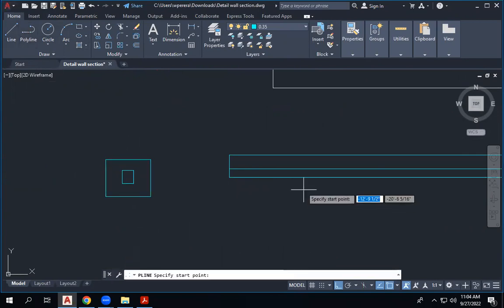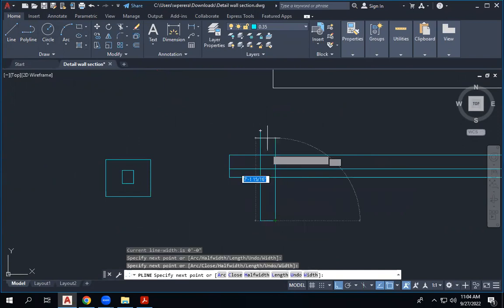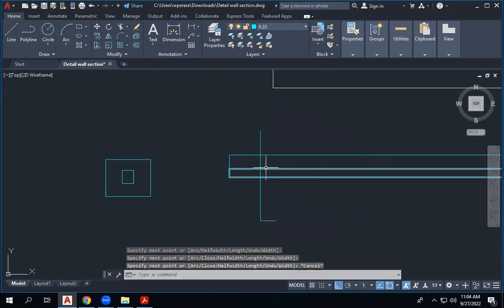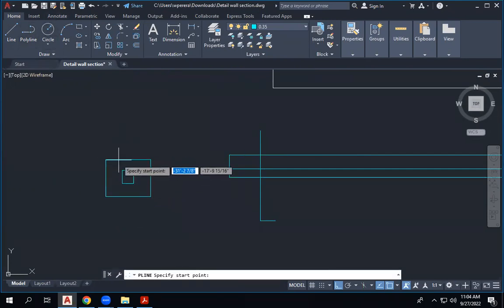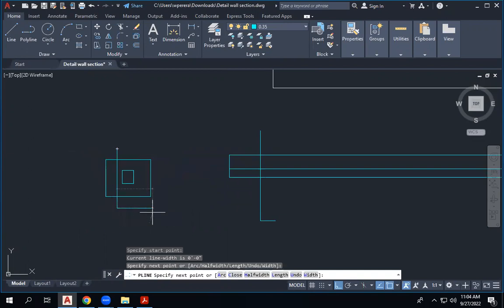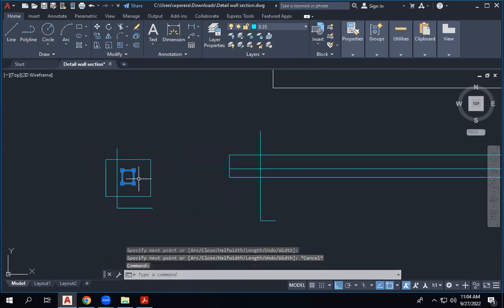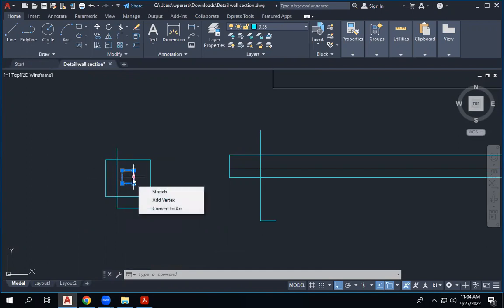So if you cut it here, you see all the way, the wall section and the footing section. But in the wall foundation here, if you cut it here, what you see is the column in elevation, and this will be cut. So it's a different way. Even though both are concrete, the hatch is different. You will not put any hatch for this one.